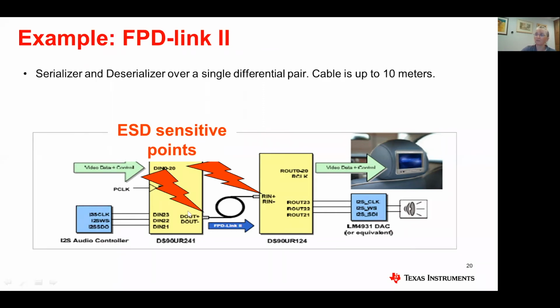So the ICs need to be designed with the ability to shunt the transient to ground on the chip. So it's more than just handling in a static controlled environment. In this case, the IC has built in this sort of large system level discharge protection capability.